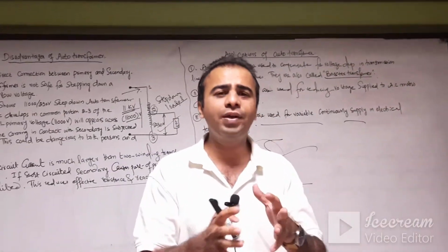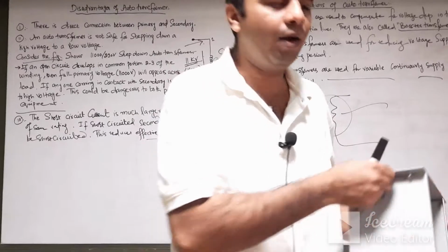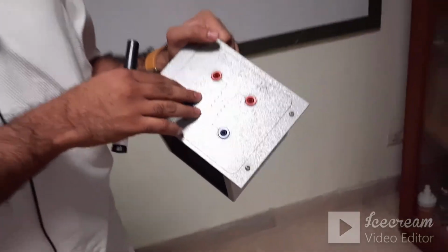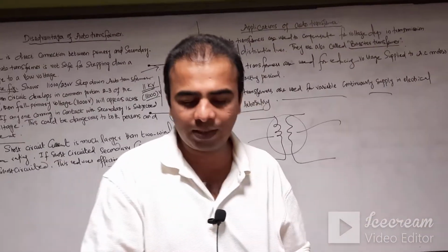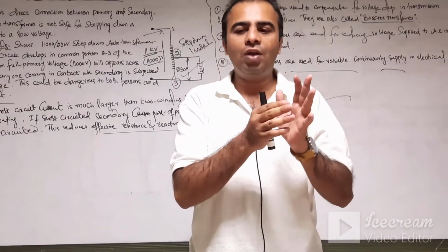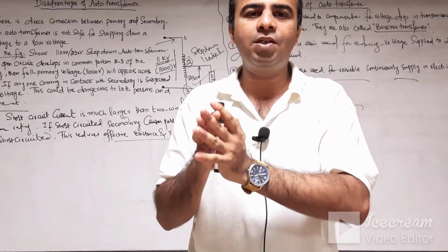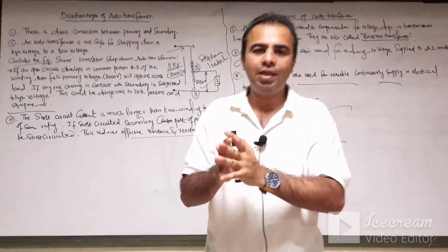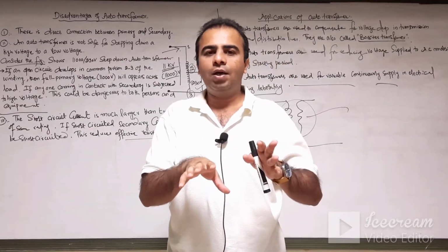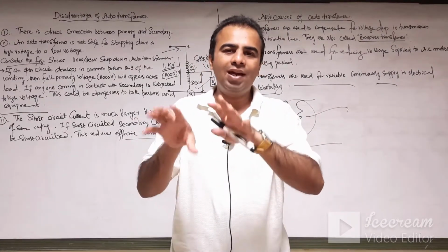Now how can you vary the supply to become 127 volts, because here we require 127, we can't exceed the voltage beyond 127 volts. So we have a 220 single phase supply, so we need a variable auto transformer to regulate the amount of voltage so that it is under the permissible limits of any electrical machine or electrical equipment, so that we can operate at the desirable amount within the prescribed limits of voltage mentioned on the electrical machines or equipment.